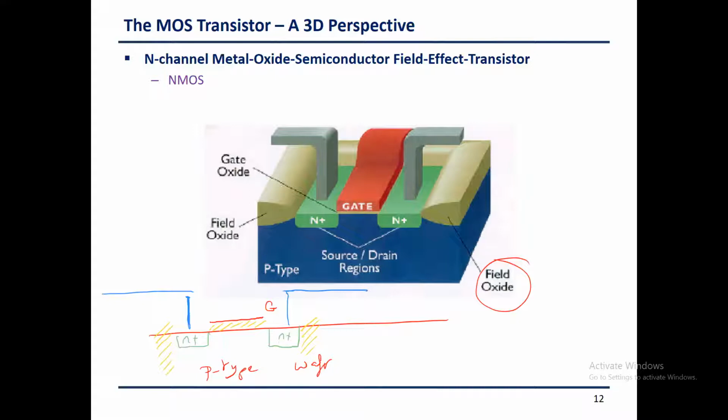Dr. Best, one small question. N-type, it also includes some P-type dopants, right? The N+, yes. It is the natural P substrate, but we shower it with a lot of ions so that the N+ becomes dominant. Because we started with the wafer, but mainly it has more N+, so it is the dominant density.